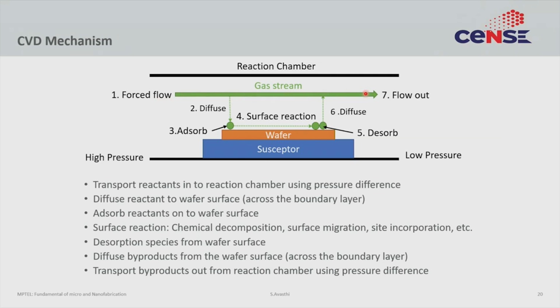We discussed some basics of fluid dynamics or viscous flow before. CVD is in the viscous flow regime. How exactly this gas flows really depends upon the geometry of the reactor, and this is where the reactor design and various other aspects come in. Once you have figured out how the gas flows inside a CVD reactor based on your application, then you must also look at how the precursor actually makes its way to the surface. In general, that happens through diffusion.